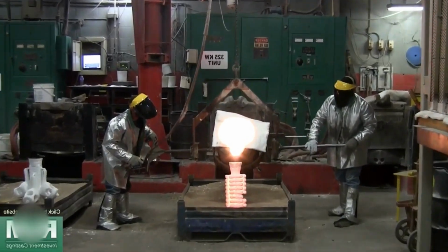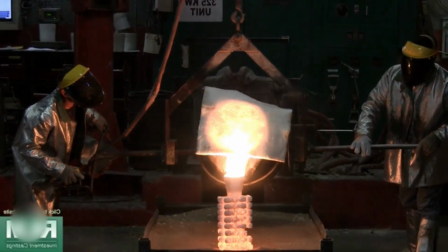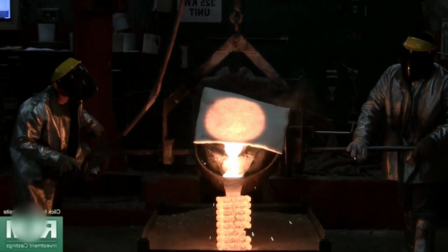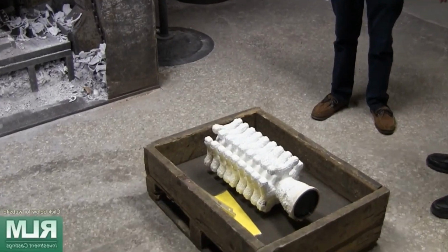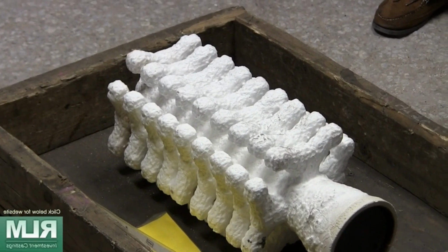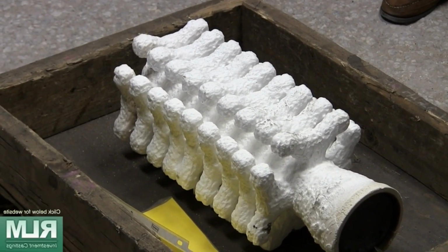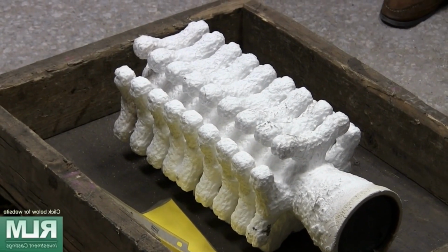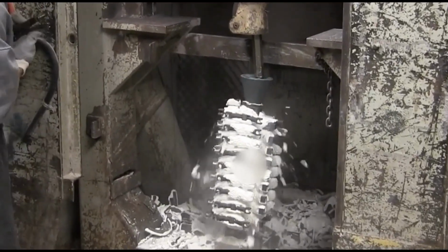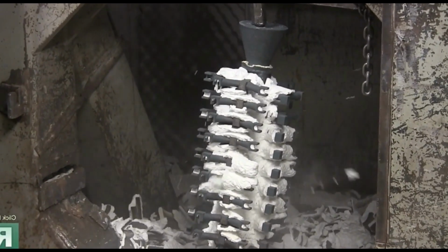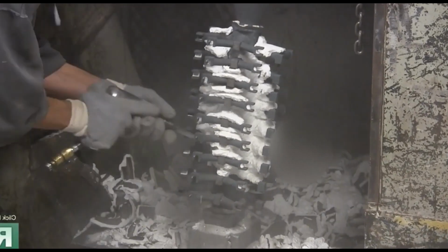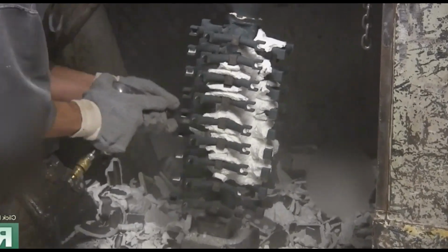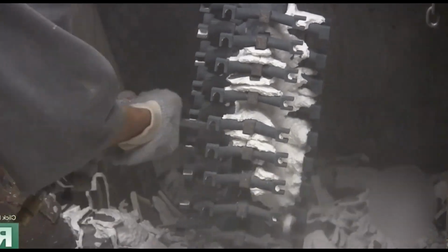The molten metal completely fills the mold cavities, taking on the geometric shape that forms the whole details of the cast component. After that, the molten metal is left to cool down and solidify. After the metal cools and solidifies, the ceramic shell is broken away, revealing the newly cast parts. There are a variety of methods to remove the ceramic shell, including vibration, blasting, and chemical cleaning.